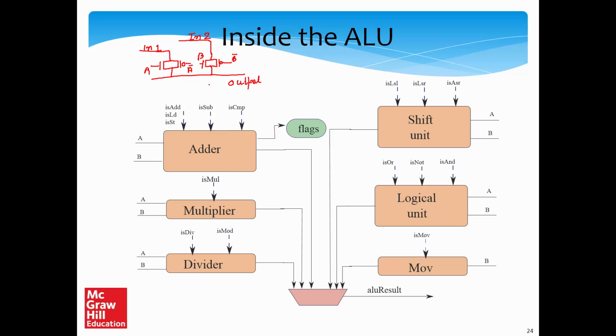Now, if you recall our discussion from chapter 6, let's say that A is 1. If A is 1, the NMOS transistor is on, and A bar is 0, so the PMOS transistor is on as well. So essentially this input is connected to the output, and the output will take up whatever voltage is there at this input.